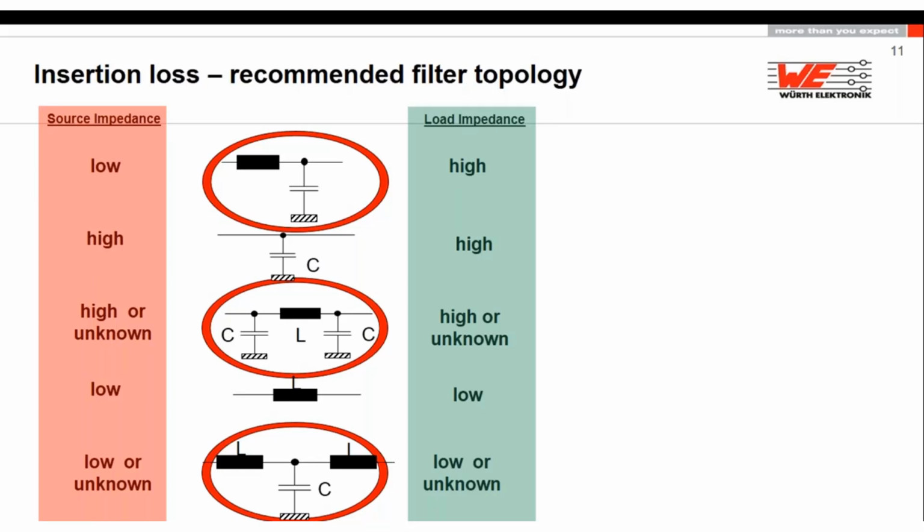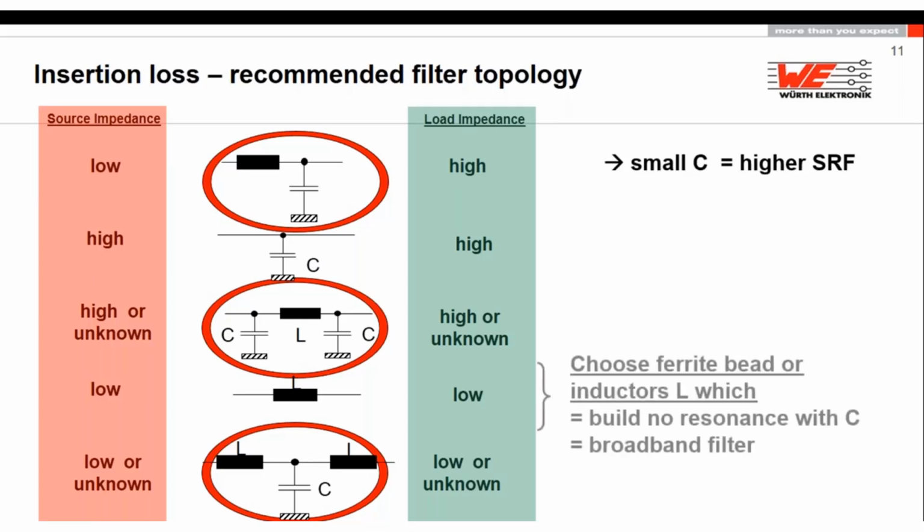For this reason, I suggest to use small capacitors, maximum 1 microfarad, with low ESL and low ESR, and for the inductor, please take care that you use a low Q factor inductance. Use chokes. The quality factor of an inductor is not a difference between made in Germany or made somewhere else. It is different. What is the ratio of impedance, the reactance, to the R losses? This is the definition of the Q factor.